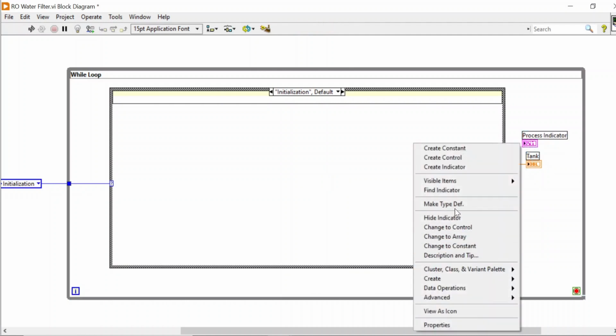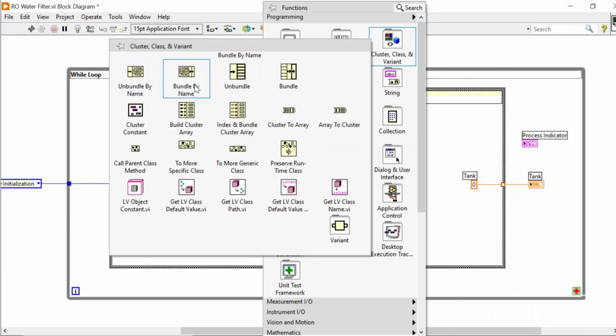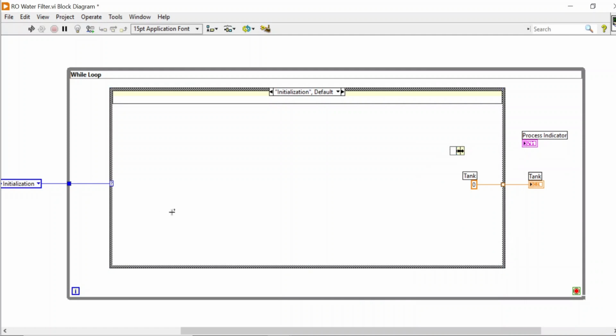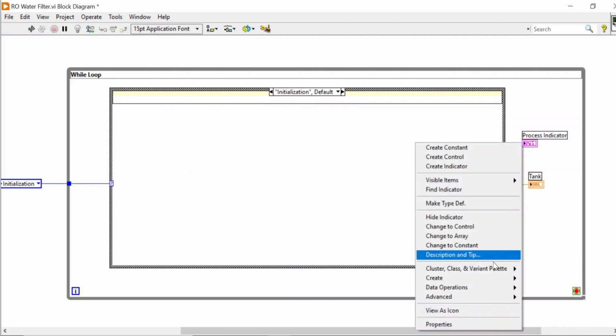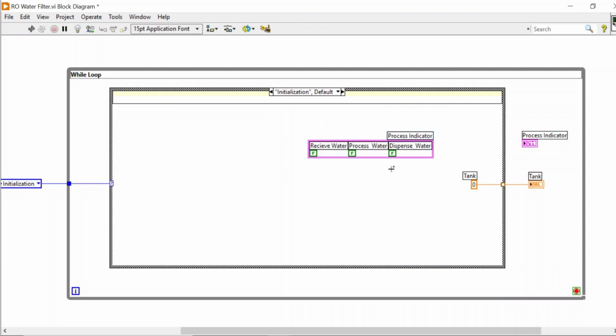On the right hand side, create constant. Let's say we use a cluster and bundle here. So before using this bundle, let's take a process indicator. Rather than taking a cluster, we can take a constant as well, right? So delete it, right click, create constant, inside the loop. There is a process indicator, and this...